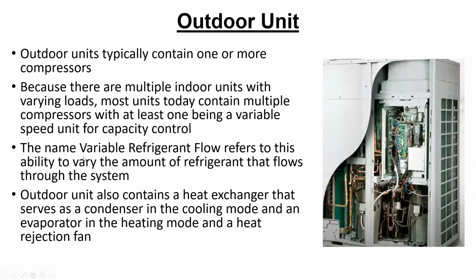They call it variable refrigerant flow because they refer to the ability to vary the amount of refrigerant that flows through the system. So based on the cooling load in each separate space or room, you can control the rate of refrigerant going to that room.